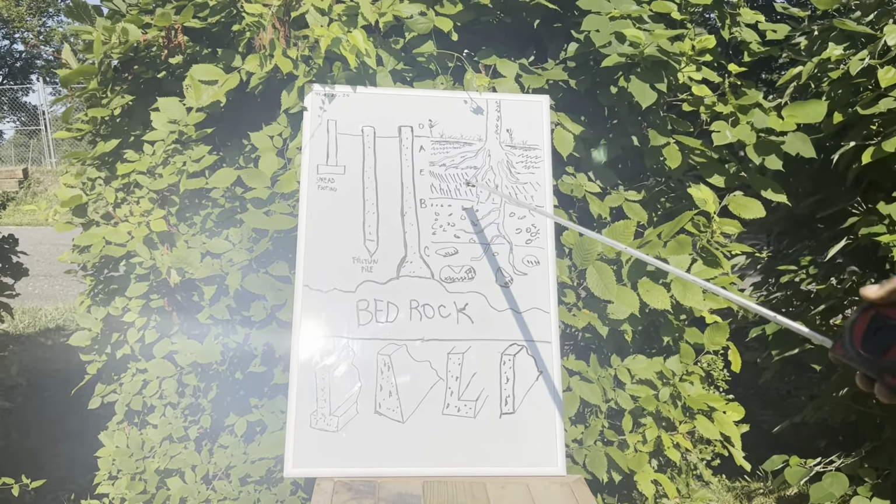See? A simple way to identify if your soil is sticky: see how it's rolling up into a ribbon? See, it's sticky, so this would be dealing with a high clay content. See that? This soil is pretty high in clay content. So clay would be sticky in your hands.